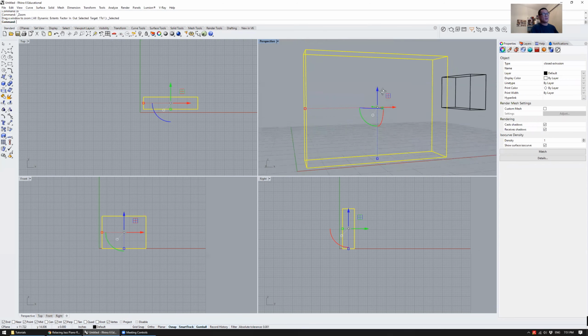So the rectangle command is right there, or you can just literally type rectangle, and it'll bring up these commands. You can click on it to execute it or press enter, right? So click on one corner, and instead of clicking on the other corner arbitrarily, I'm actually going to type in 15, enter for one end, and you'll see that's the width, and 15 for length, and then 15 again.